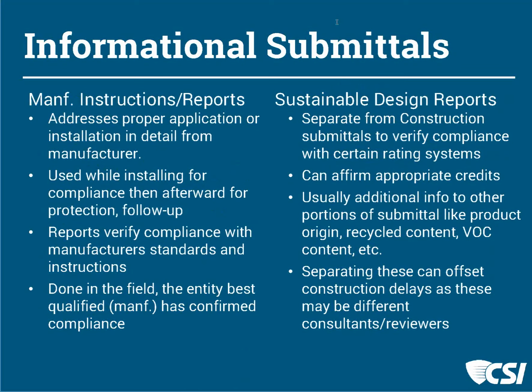Also, sustainable design reports, how the contractor is tracking the materials, you know, as part of recycled content. Also that the contractor has on site materials that meet our VOC content requirements for the project. These are separate submittals that can be critical to receiving some sort of certification or rating for the building, and so these are used to document that sort of information during and then particularly at the end of a project.